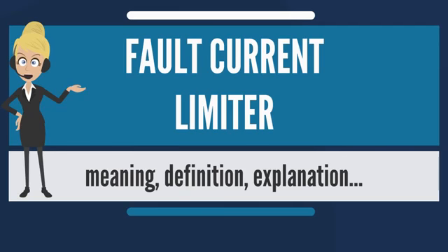Electric power distribution systems include circuit breakers to disconnect power in case of a fault, but to maximize reliability, they wish to disconnect the smallest possible portion of the network. This means that even the smallest circuit breakers, as well as all wiring to them, must be able to disconnect large fault currents. A problem arises if the electricity supply is upgraded, by adding new generation capacity or by adding cross connections. Because these increase the amount of power that can be supplied, all of the branch circuits must have their bus bars and circuit breakers upgraded to handle the new higher fault current limit.